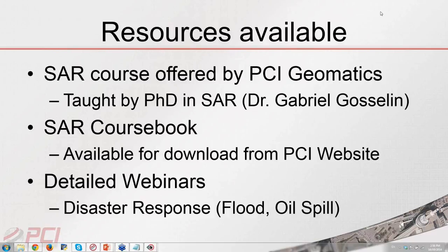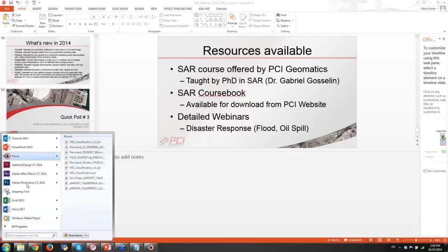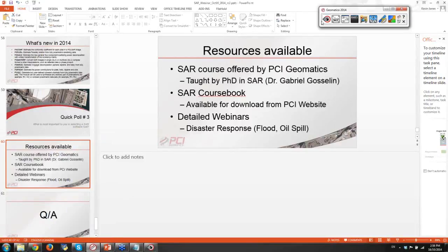Sure. So it's pretty simple. We have different modules available within our software, starting with the absolute base product that we make available, known as Geomatica Core, and what that does is it allows you to essentially view imagery, manipulate, do contrast enhancement, histograms, load support for all the different data. A lot of the automation capability is not available within Core. You have to move up to Prime. Once you move up to Prime, you have access to the scripting environment and the modeling environment.